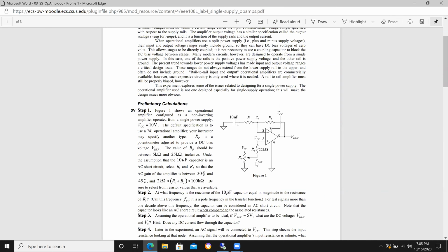Well, we purposely picked VREF to be 2.5 volts. So it's right in the middle between 0 and 5 volts, DC-wise, right? So your circuit goes up and down right in the middle between 0 and 5 volts. Well, now whatever voltage you have here is getting gained up between V in and V out by 45.